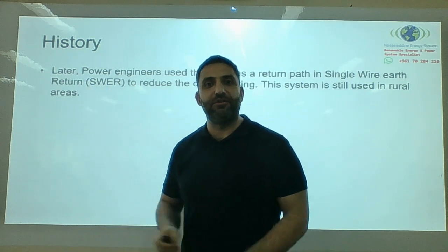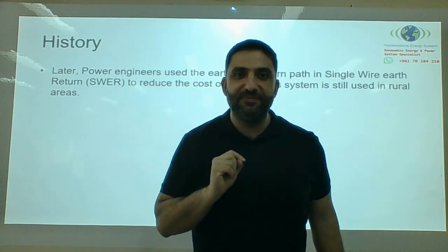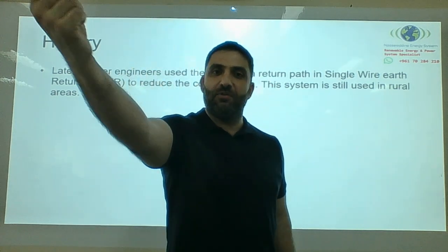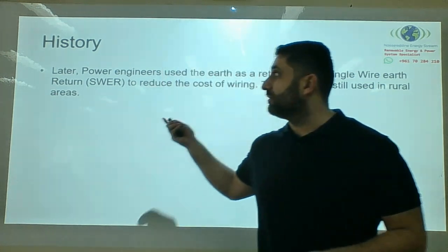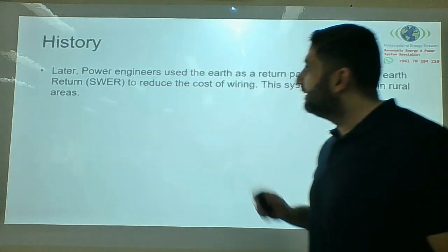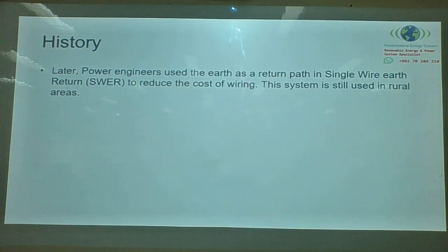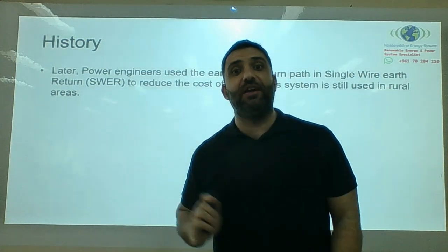Single wire earth return. So instead of having two wires, active and neutral, where one will send and one will return the power to close the loop, the circuit, they said, hold on, we can use single wire earth return. And this reduced the cost of the wiring system. This system is still used until now in rural areas.